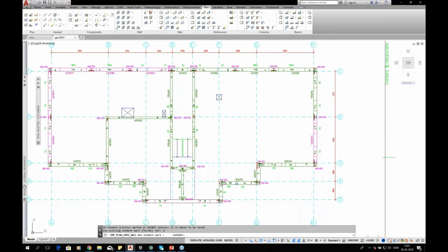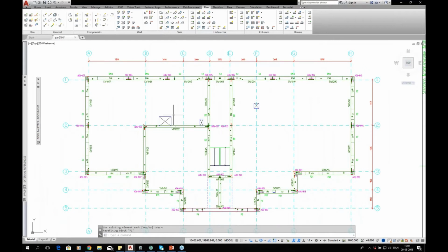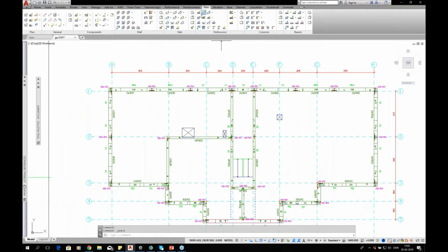And now you can see that I give a new name for this one. This is because if we have several elements that are the same, we want IMPACT to only create one drawing of these. So let's say we had 5 walls that were the same. We only want one drawing that says 5 pieces. We can of course also print this one drawing in 5 copies that will specify each and every element. This is relevant for walls, but even more relevant, of course, for hollow cores, where we often have a lot of hollow cores that are completely identical.